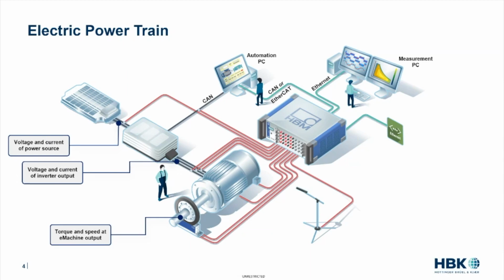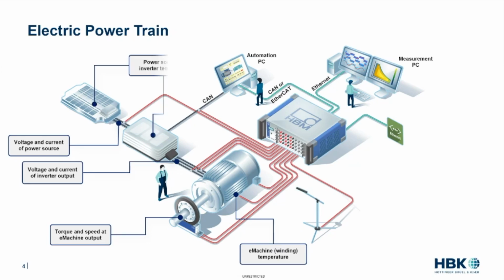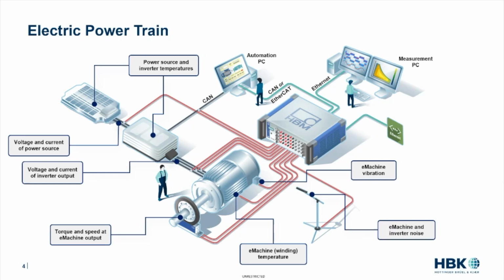And then there are a lot of secondary parameters you also might want to measure, like temperatures in the machine, in the battery and in the inverter, and vibration signals to understand the NVH characteristics of your drive, which is also potentially done with a microphone. So that is what we are talking about today, how to measure a typical electric drivetrain faster.